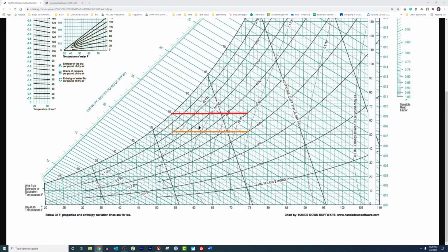But your real concern should be condensation and buildup in subcooled areas, like a subcooled plenum, or walls that are maybe exterior exposed and they get cold during the day. Brick is notorious for this. A lot of these older buildings with brick walls, it gets cold at night and those walls retain that temperature and they stay cold, and you'll see the walls will just feel slick because of that condensing effect, because those walls are lower temperature than ambient.